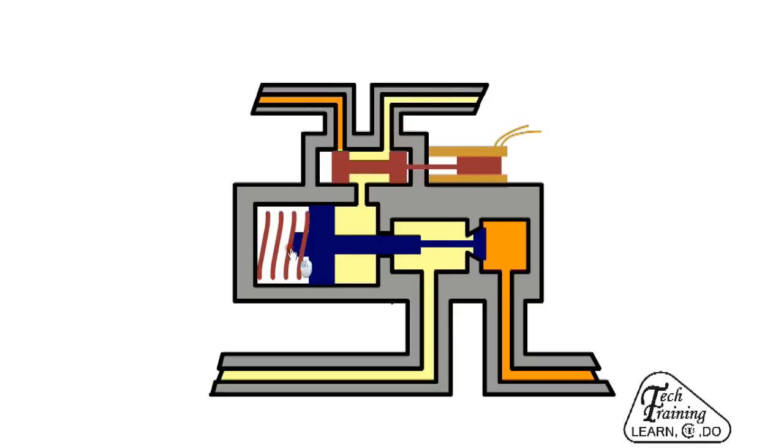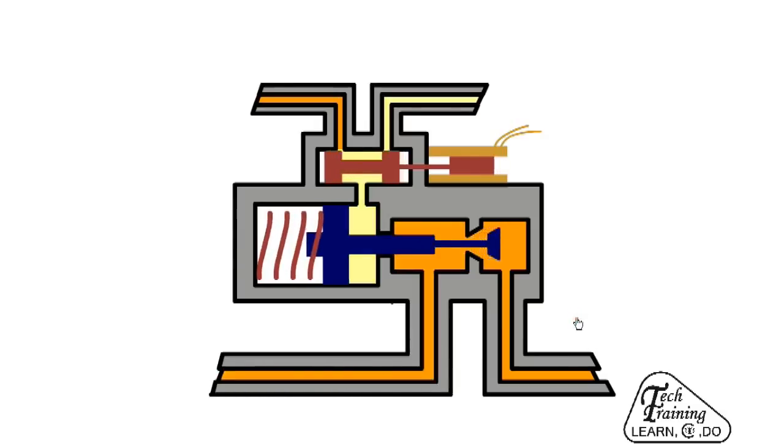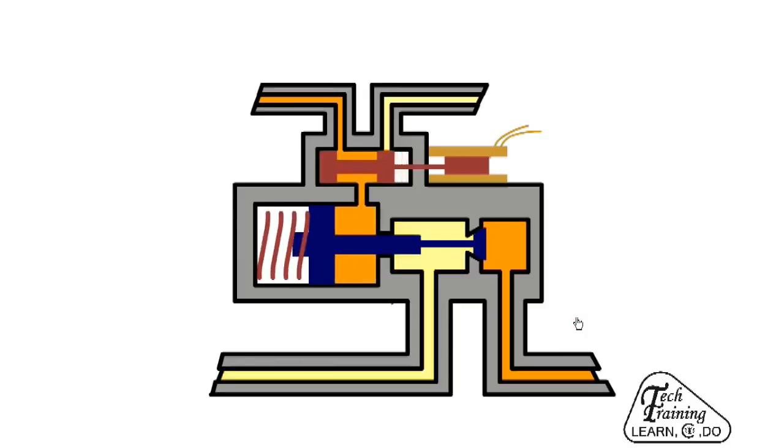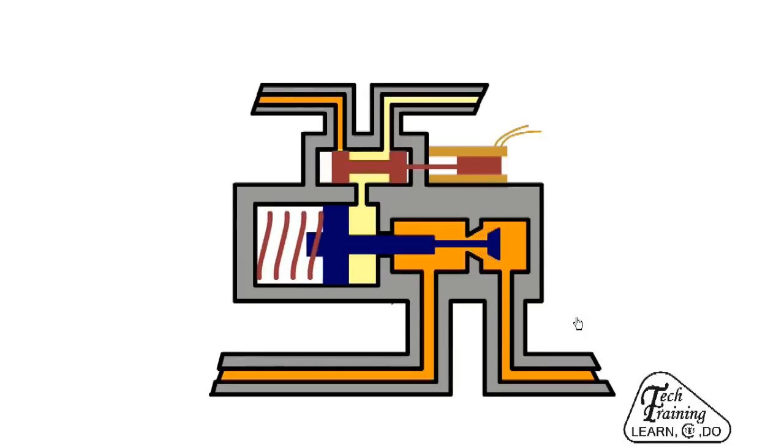The spring force opens the valve, and the additional rod volume also increases the fluid pressure and reapplies the brakes. This cycle can happen 20 times per second and results in a pulsing sensation in the brake pedal. ABS pulses the brakes on and off. It prevents the wheels from locking, the car will stop in a shorter distance, and it can be steered.